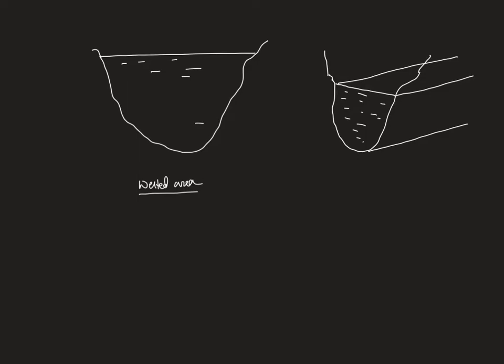So here also the way of calculating is the same. Suppose the height is h, and here you take y and dy. Here the width is not constant, the width varies. So I'll keep this area as dA only. I will not write it in terms of the width because the width is not constant. So here this is a force dF acting on this area dA.